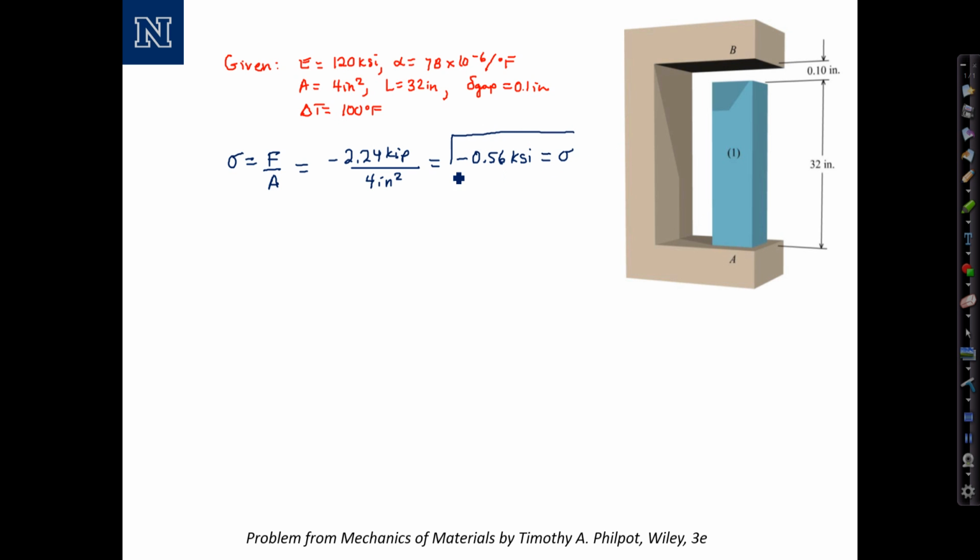This is a relatively small number for a stress. However, part of the reason for that is because the elastic modulus for this polyethylene material is rather small. It's more similar to rubber than steel. So that is why we get a relatively small stress in the member. It is a compressive stress, which we logically understand it to be once it hits or closes the gap.